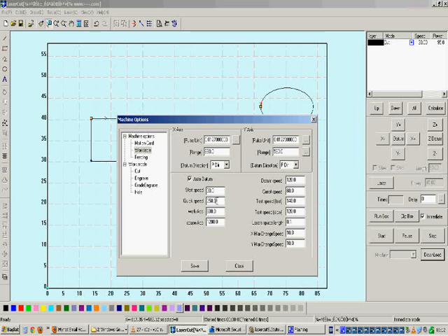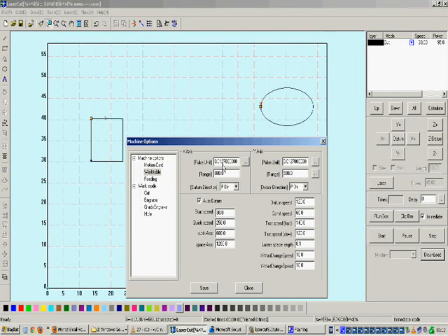Using a 250 mm per second value is enough for most operations. Using too high values will again cause the machine head to work with impact, so it will damage your machines in the long run. By the way, the speeds in this menu are all in millimeters per second.